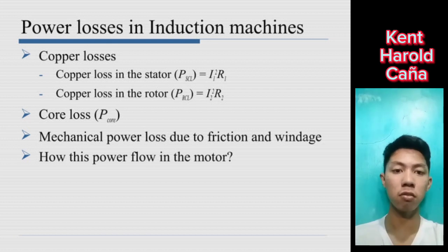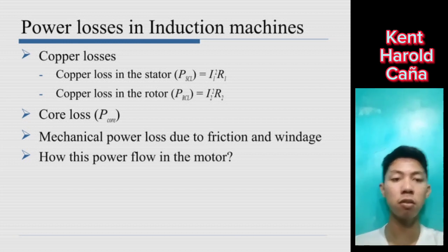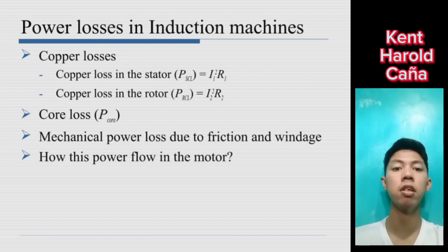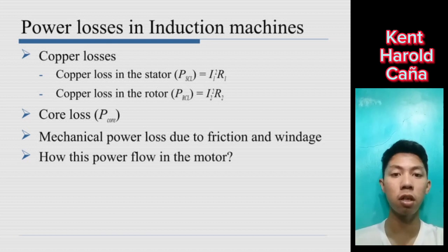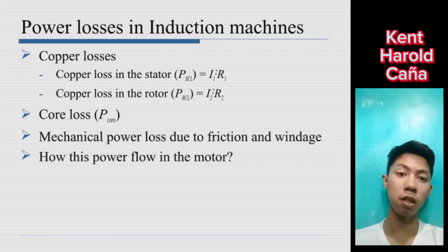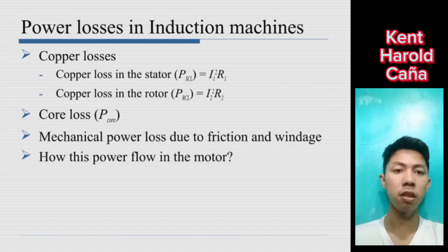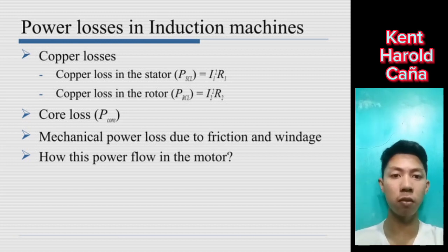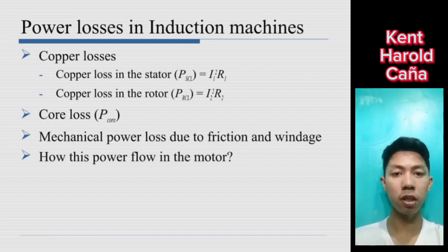It analyzes the contributing factors including core losses, copper losses, stray losses, and mechanical losses. The implications of higher power losses on machine efficiency, potential heating issues, and overall reliability are discussed, highlighting the importance of optimization in various industrial applications. Mitigation strategies such as selecting quality core materials, optimizing winding designs, and employing advanced cooling techniques are presented as crucial